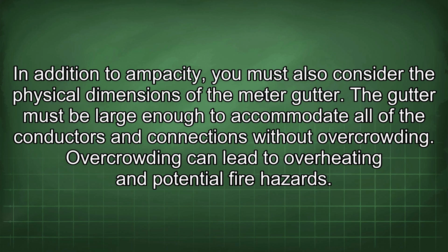In addition to ampacity, you must also consider the physical dimensions of the meter gutter. The gutter must be large enough to accommodate all of the conductors and connections without overcrowding. Overcrowding can lead to overheating and potential fire hazards.